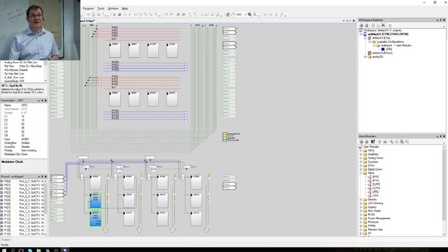I would guess so, since they are 38,400. Well, maybe. I'll do it in any case some other way. So this is one way. We already had VC1. That's a 3 megahertz signal divided by 430. That's about 7,000. That's an awkward number. How about 15 times 8? 120. Yeah, that's closer.